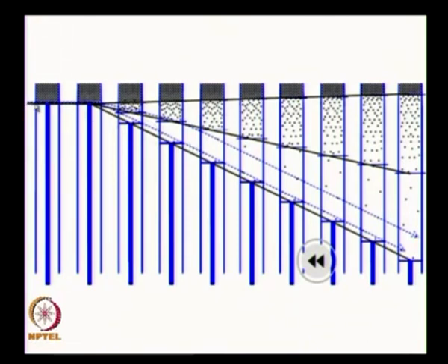What I wanted to show now is this streamline drawn here. We said that it is tracking of a particular particle, especially this one and this one, as a function of time, and that becomes your streamline if you look at it in 2D flows. Now what I want you to see is they are starting very close to each other, that is, the gap between them is very small. If you go back to understanding fluid mechanics, the stream tubes can be considered as the streamlines in this case in 2D flow, right. The streamlines will form the stream tube in 2D flow.